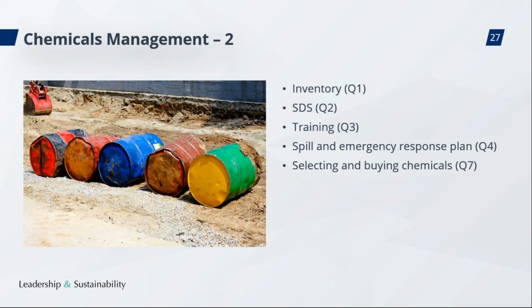Another question is related to SDS, safety data sheets. In my experience, many factories need to improve here too. Either the SDS are not available, they are very old. We have even seen SDS that are 10 years old or older, or they are not available where chemicals are used. And please, and this is really for the safety of the workers in the factory, please have the SDS readily available wherever chemicals are used or stored. Really important. And when we do the verification, we will check on this.